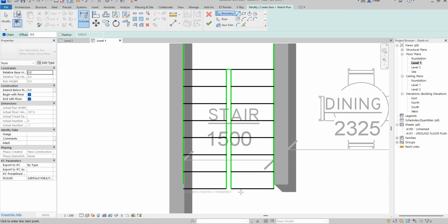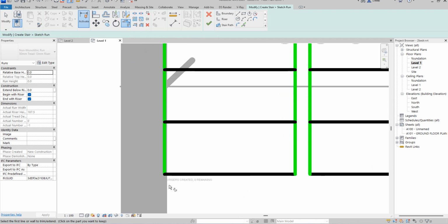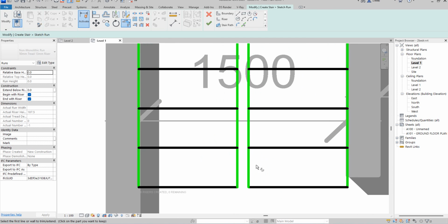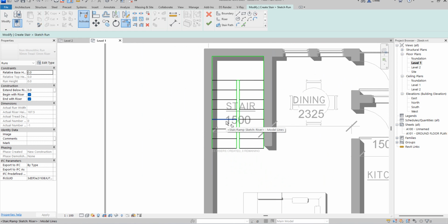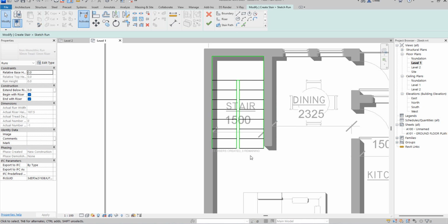Now what else do we need to do? You can decide to leave it and check whether what you have created will work. Now look at it. How many risers are created? Six risers created, and there's only one side that is showing. The reason is that it has not been joined together. You can do that by running it and seeing how far it flows before you conclude your riser. So let me quickly do that. I will come back and edit this.